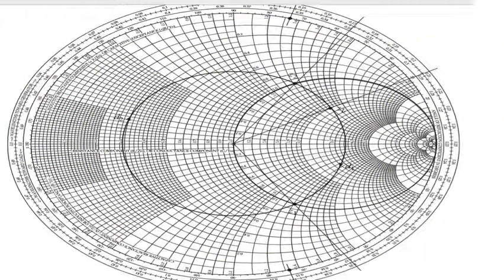I've come back to the similar circuit. To find L1 and L2, first you need to find the Z1 point, if you remember that. Where is your Z1 point? This is your Z1 point. Am I right? Clockwise direction, right? This Z1 point, I am supposed to write its complex conjugate. Do you remember that? The real value is always 1, but the imaginary part has to be cancelled out. So the complex conjugate that I take will always be the Z2 point.